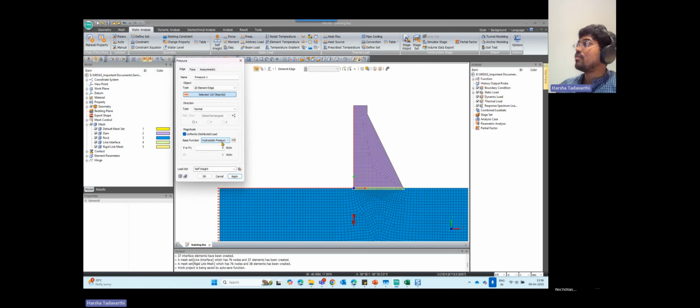The values that we inputted are dimensionless, so we need to provide dimension and the units here. Hence we will multiply it by 1 kilonewton per meter. So the units will be assigned to the values that we have inputted in the base function. This will act like a multiplier here. Then in the load set name, we can define it as hydrostatic pressure.